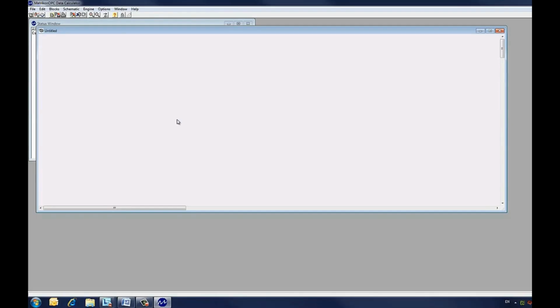We will use the Matrikon OPC server for simulation as our OPC server for both our input and output. We will read in a value from Bucket Brigade Real 4 as our Celsius input, convert the value, and output to Bucket Brigade Real 8 as our Fahrenheit output.